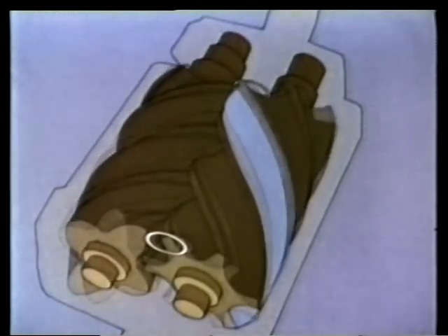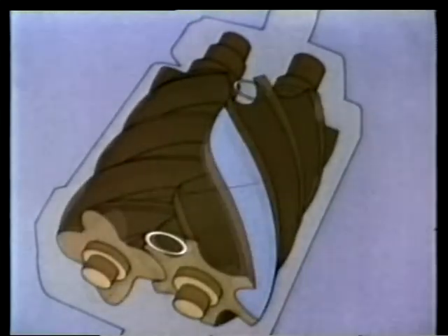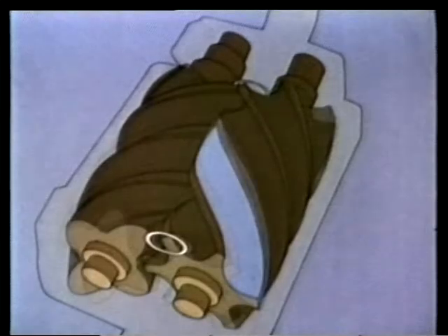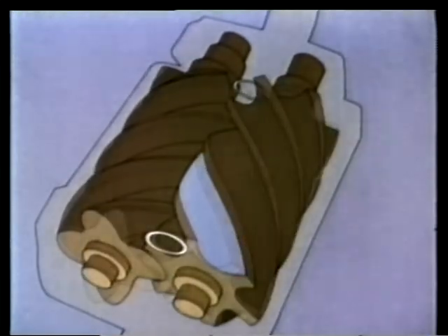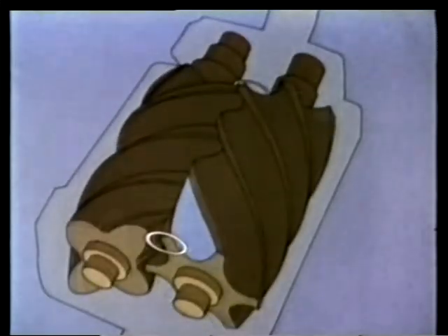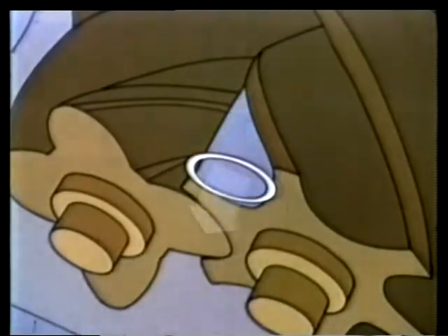As the rotors turn, one lobe of the main rotor meshes with the air-filled groove, forming an air pocket. More rotation causes the air pocket to get smaller as the main rotor rolls farther into the secondary groove. The air is squeezed down toward the end of the groove. When the far end of the groove passes the discharge port, the compressed air is released into the discharge piping.